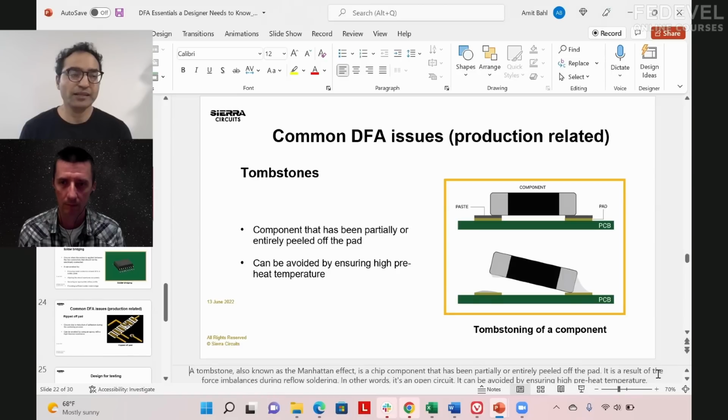And the only way that a PCB fabricator knows to do that is if the designer tells them. And the only way the designer knows to tell them is if the assembly shop gives feedback saying that a lot of solder wicked into that hole and it should be filled. Or, you work with someone like us who's looking at both the fab and the assembly together and trying to give that feedback up front. So that's our DFA, DFM process.